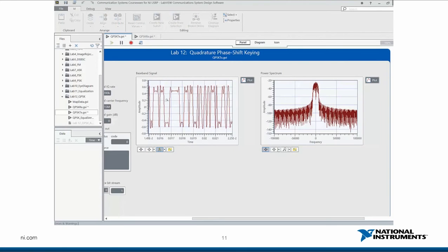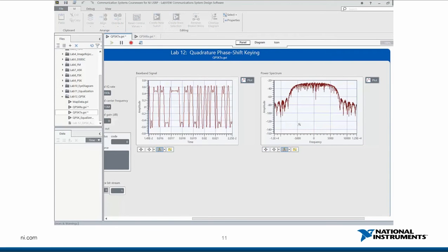Again, if we just use some quick graph tools, we can make a quick verification on roughly the bandwidth of what it is we're sending. And that looks to be in around about the sort of 200k range after we've applied that pulse shaping filter. Now what we can do is switch over and run the receiver code.